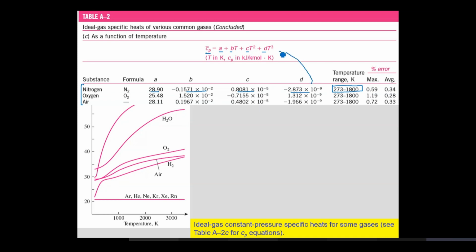If you plug these constants into this equation, you will have essentially an equation between Cp and temperature. So you can plug in that relationship of Cp(T) in the equation and integrate with regard to dT from T1 to T2. This would give you delta H for that specific gas between T1 and T2. But the calculation is very hectic. This is one way to find delta H or delta U, using the exact relationship between Cp and temperature to find the integral of Cp(T) dT.